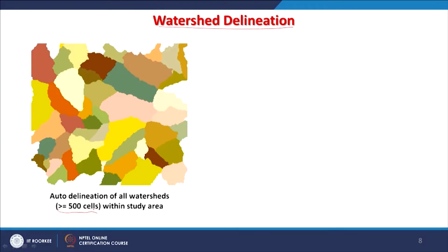One problem I mentioned earlier in the previous lecture, which I am going to repeat, is that while doing this you will have problems or limitations of surface hydrologic modelling along the boundary or margins of your input digital elevation model, which you can see. Because remember, one watershed ends, another starts. Here we do not have a continuous digital elevation model for the entire globe, only a part of it. So, this area will contribute to some other outlet, maybe like this, and therefore it is not part of this basin, and therefore it has not been delineated.